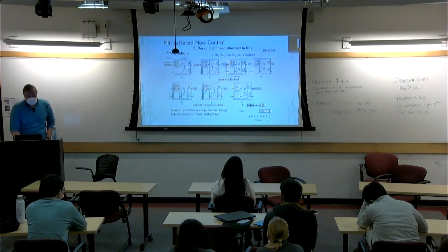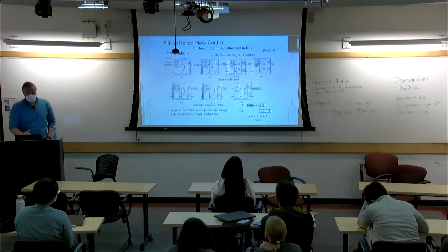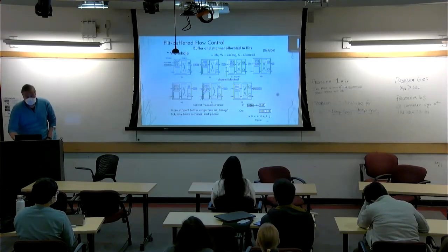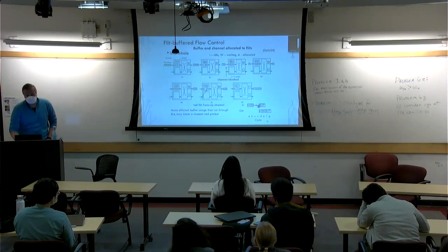But in this case here, let's say the channel is blocked for some reason, because both of these are full. So I can't advance the third one. Only when the switch is allocated can I advance the head flit and then accept another body flit. But I'm still making progress, right? I pushed out at the input, I had these two, then I had nothing. And then at the output, I got them all assembled without the delay.